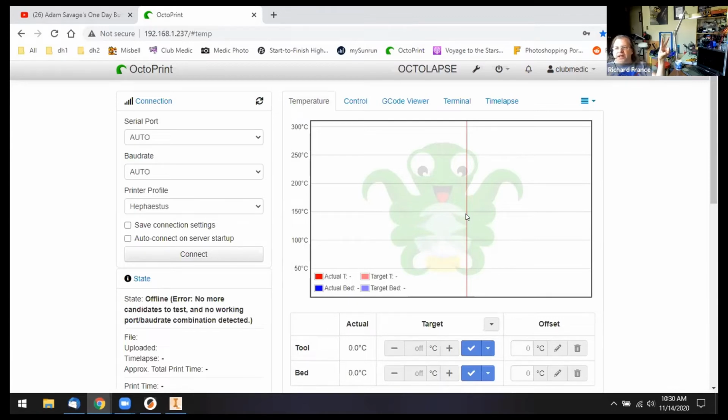And B, how different, because different brands of filament will cause temperature swings in your head, and you can see that, and you can adjust. Once again, the finicky details of this stuff I was talking about earlier: you can adjust your print temperatures for certain brands of filament. And so this is a really good way to watch that.